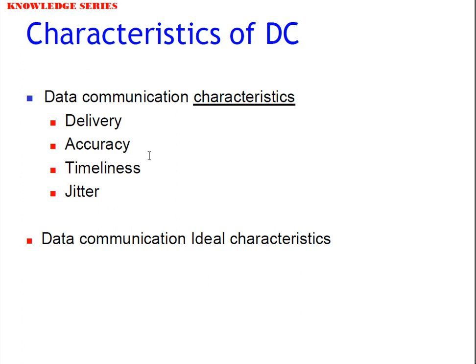The second content parameter is the channel over which the signal is transmitted to the receiver. The channel should not be too noisy, otherwise it will corrupt the message, and there should not be restrictions between the transmitter and the receiver. Particularly in microwave communications, we say line of sight. Line of sight means the transmitter and the receiver should view each other. If some obstacle, say a building, comes in between, then proper signal transmission will not take place in the case of a microwave.